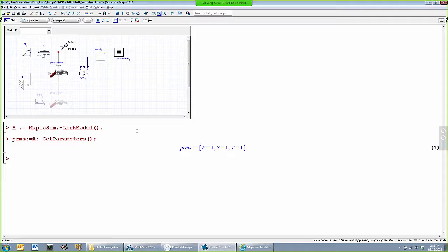Now I use the command from the MapleSim package called getCompiledProc, and what it does is generate the equations, create C code, and compile them. Basically what I end up with is a function that I can call over and over again, and it benefits from the symbolic optimization of the equations and code generation. So it is basically the underlying function for our multi-column analysis, for our parameter sweep, and also all sorts of optimization. Here we are going to use it directly.